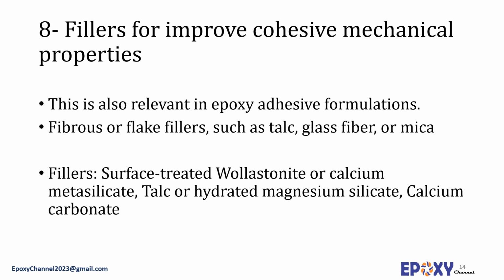Only certain fillers can be used to increase the cohesive strength of the cured epoxy adhesive formulations. Generally, fibrous or flake fillers such as talc, glass fibers, or mica will bring about a certain degree of increase in the tensile and flexural strengths. However, for significant increase in physical strength, a relatively high concentration of the fillers has to be used.